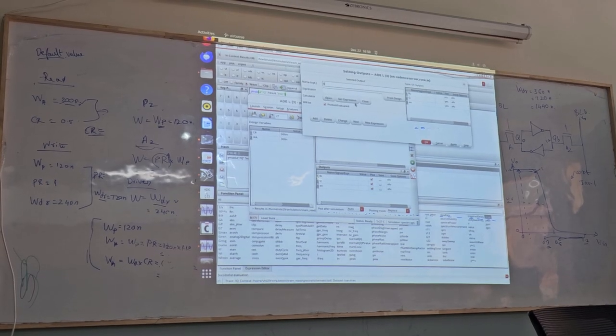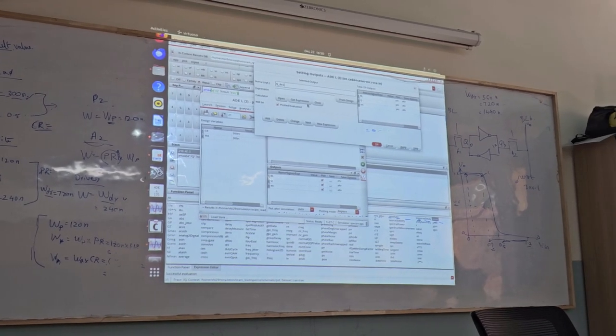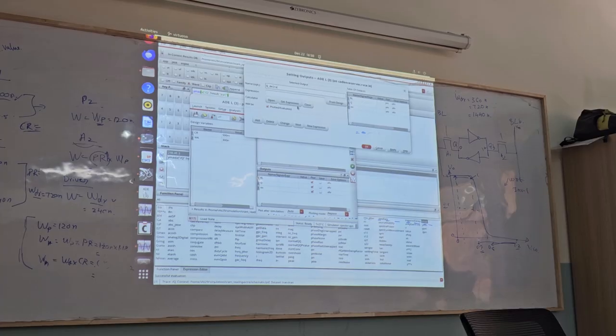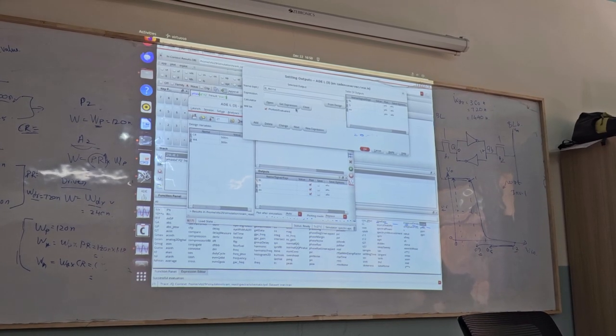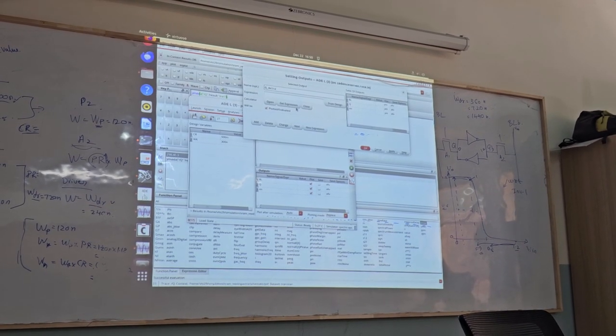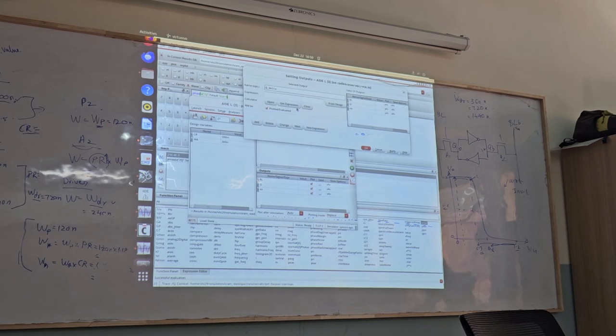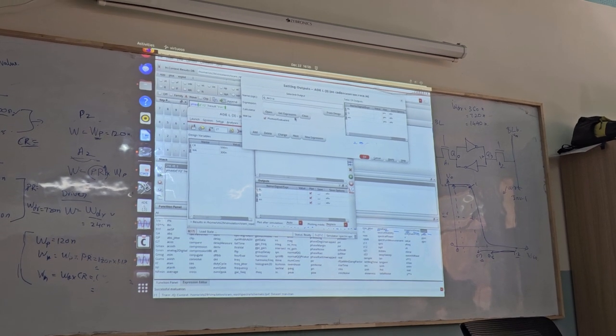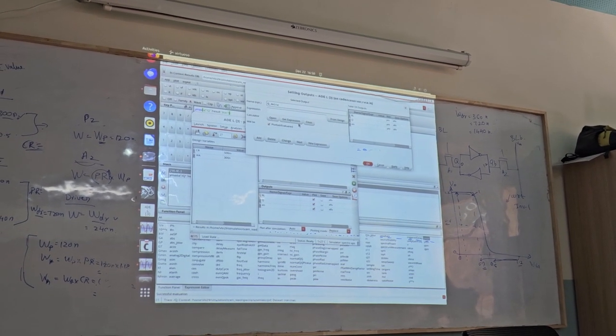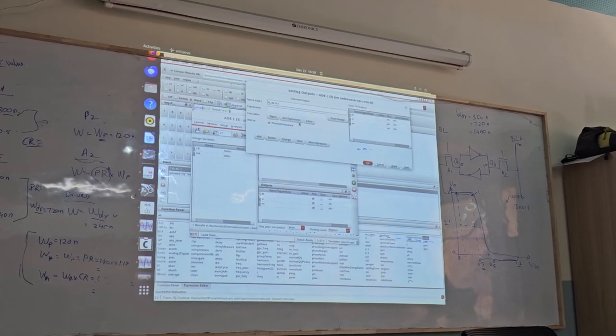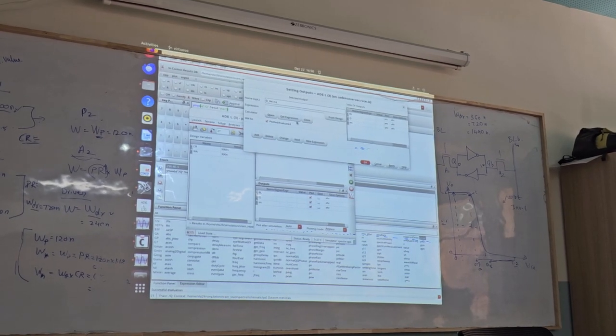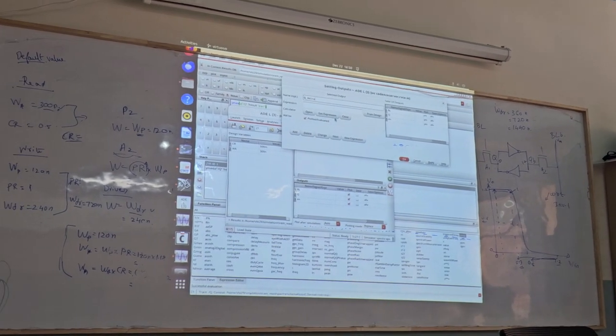Excuse me, sir. Isn't it supposed to be 600 millivolts? Because in the beginning you told it is 1. Yeah, it would be 600. Yeah, but because it's a capacitor, while it is trying to rise up, the voltage across the capacitor keeps losing. So that's why it doesn't reach all the way to 0.6, but rather somewhere in an intermediate value.